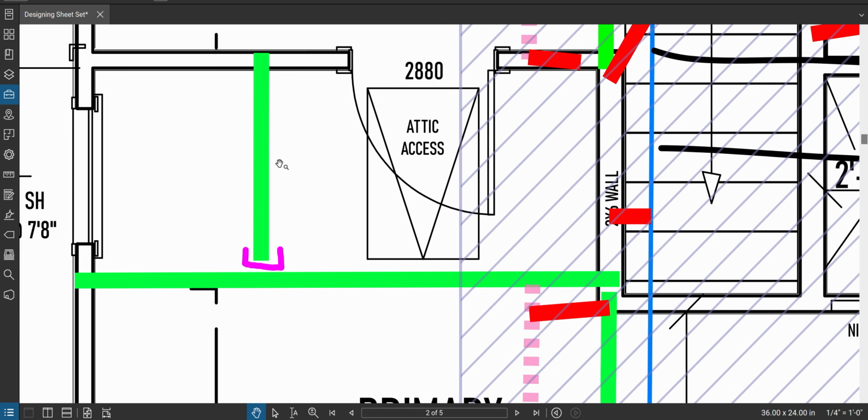And on the roof plan, this is right where that roof pitch happened. This pitch change happened from the dormer. Let me show you that real quick. Oops, wrong way. It's right where this happens. So what we're going to do is we're going to take the width of this guy, and it's going to be our tributary load, tributary width for the roof loading. So let's go back and do that real quick.